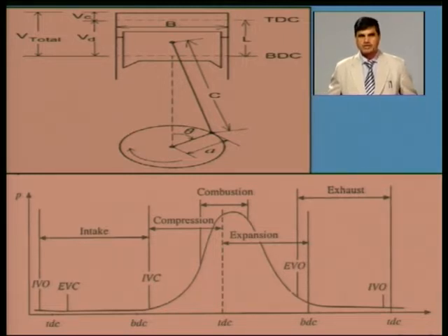that it is not exactly constant volume combustion. If constant volume combustion is there, then the efficiency of the cycle will be much more. If it is taking some time for the combustion, the efficiency is going down. So theoretically, if I am saying we need constant volume combustion without giving any time, the total heat which has to be supplied in the cycle has to be added. But in actual cases it is taking time.